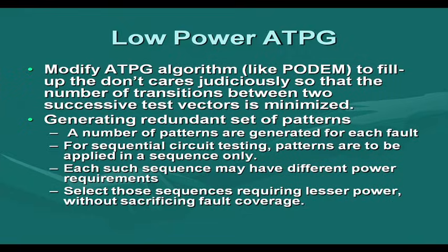In this way we can generate a redundant set of patterns. Now, most of the ATPG algorithms, when you generate this n detect pattern set, do not do any compaction of the test set. So, for every fault, say n equal to 2, I get 2 patterns. If there are k faults in the circuit, I get a total of 2k patterns. So, there is no compaction done.